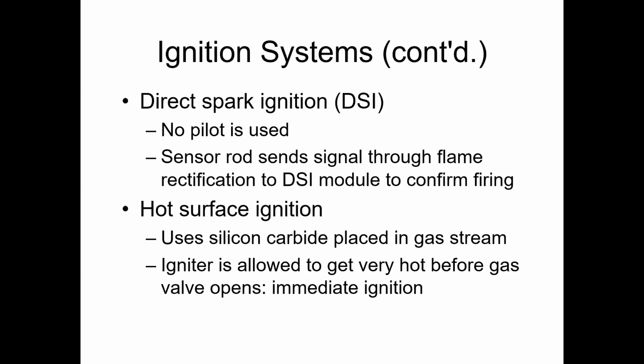Not the only thing I had to repair, not the only thing I replaced, but definitely one of the most common parts to wear out. Again, hot surface igniters sit inside of the flame after they make that ignition. They're taking in incredible amounts of voltage and holding on to it. They wear down because of this, but they're very precise and they're cheap, so replace them often.